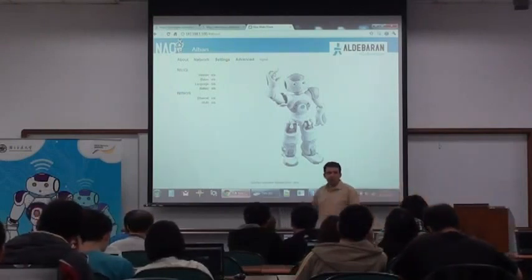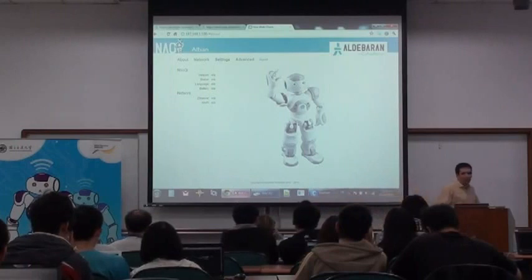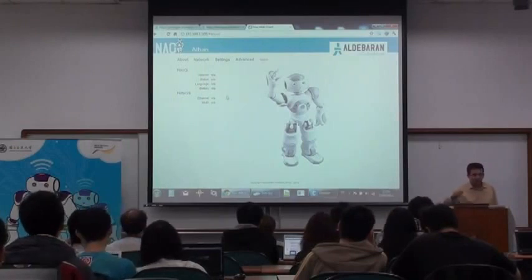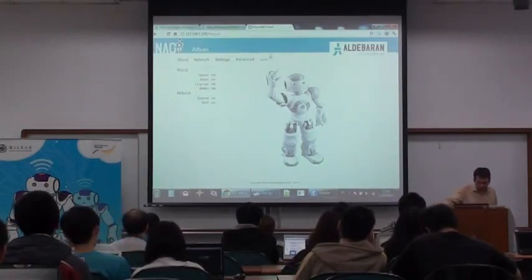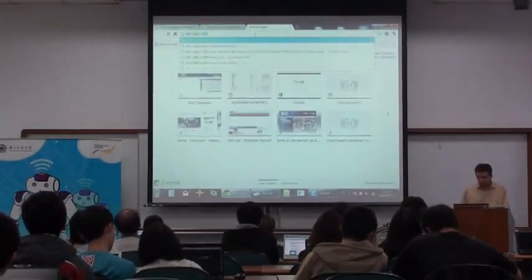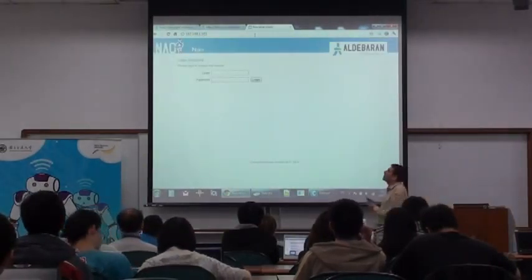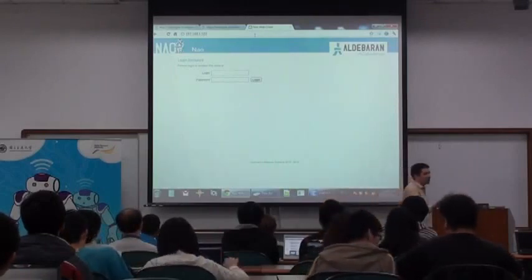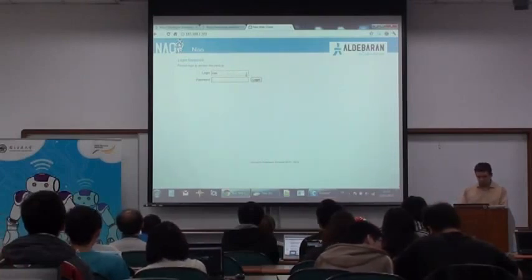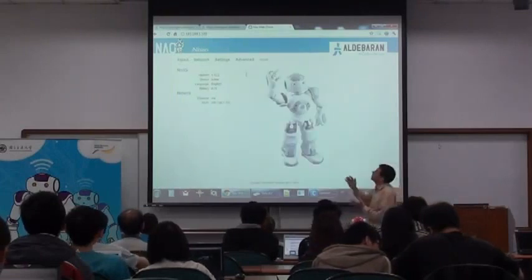Like I just showed you, you press one time and it gives you this IP address. Once you have the IP address, you can type it in your web browser. Then you have to log in on the robot. You type the login and password, which is NAO, NAO, the same, and then you enter into this web page.